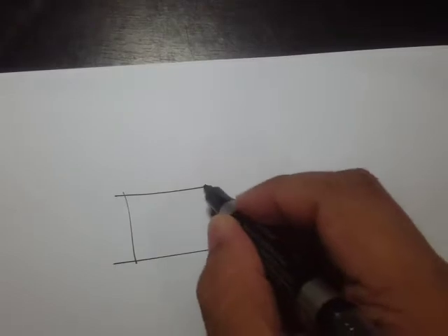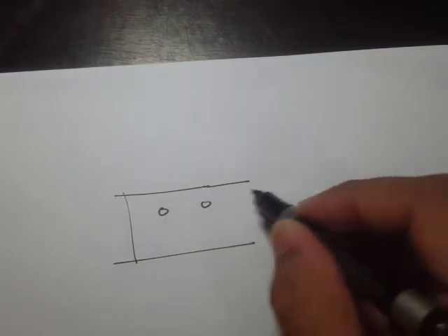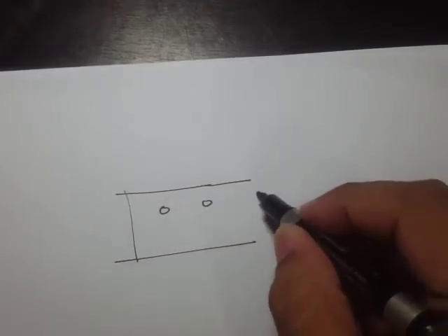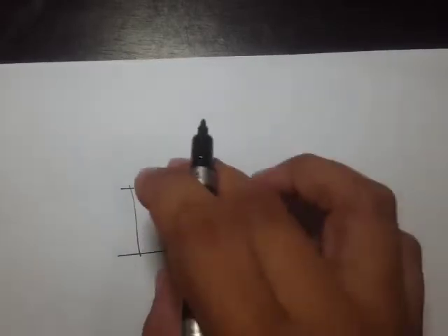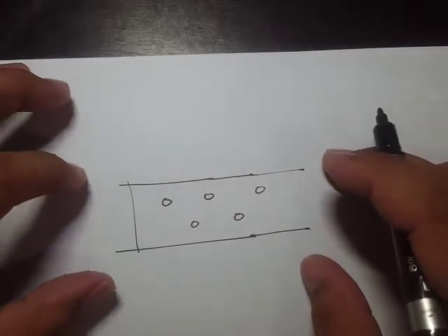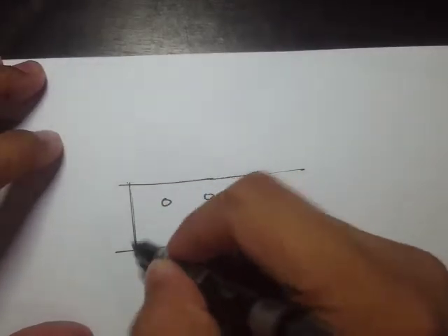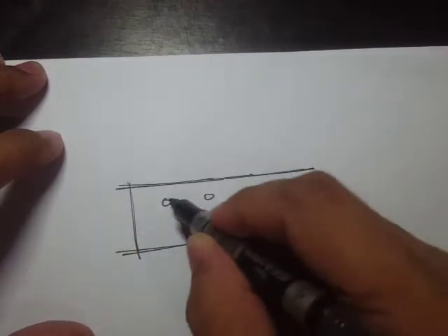Alright, we will continue our topic on tension members, and here we will discuss in detail what happens if the bolt configuration is a staggered one rather than the inline bolt configuration. When I say staggered configuration, it will look something like this. Let's say we have this first row, then the second row is actually staggered, as compared to the previous discussions that we had, which was just an inline configuration.